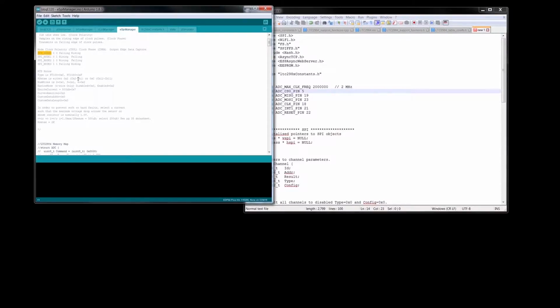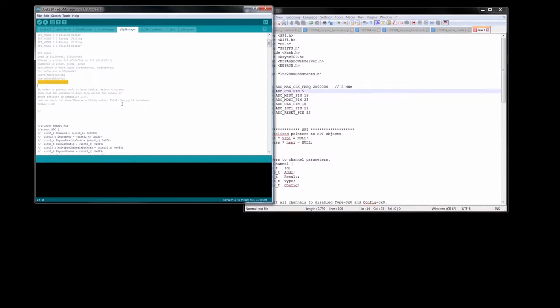Here's some RTD notes for the PT100 and PT1000. See, our RSense is on channel 2-1, which is, this is a hex value for that, or 0C for channel 12/11. This is for differential measurements. And these are the number of wires of the RTD. 2-wire is 00, 3-wire is 01, and 4-wire is 02. There's an excite mode, excite current, which RTD curve we're going to be using. And we don't have any custom data.